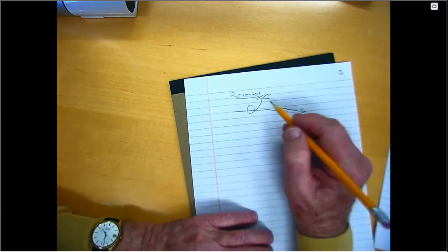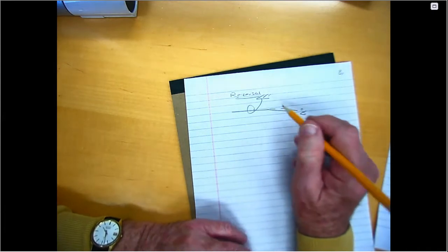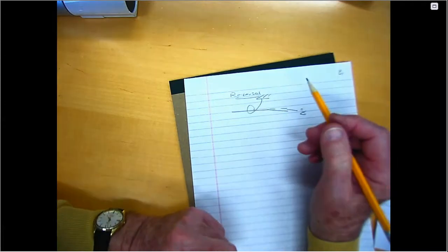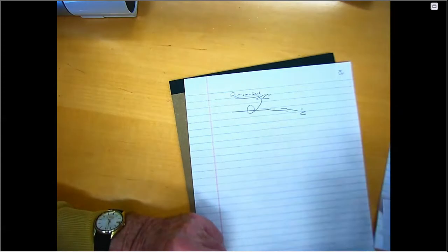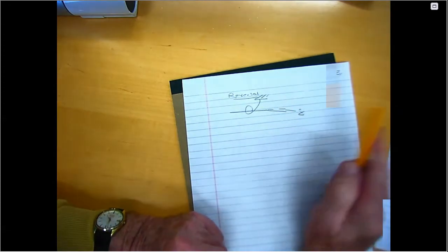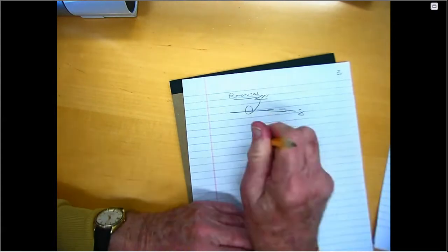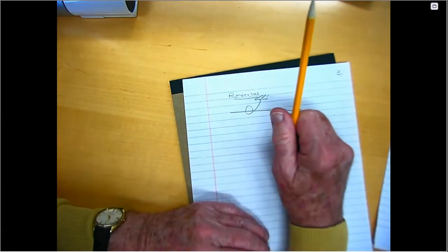I mentioned earlier, if I increase the lift on this system, I'll generally change the alpha, the twist on the spring, and that effect may be opposing the desired effect of delta increasing the lift. In fact, there can be a condition where the total lift, due to both the spring rotation and the delta, goes to zero. That's what we mean by reversal.